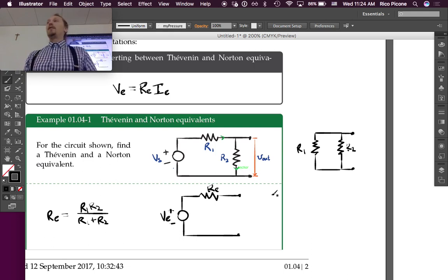Now, conveniently, as was pointed out a moment ago, we have a voltage divider circuit. We could go through the full circuit analysis, KCL, KVL, Ohm's law, like we did last time, but in lecture 1.3, we did a voltage divider circuit analysis, and we found a formula for how to get the output voltage given an input voltage across series resistors.